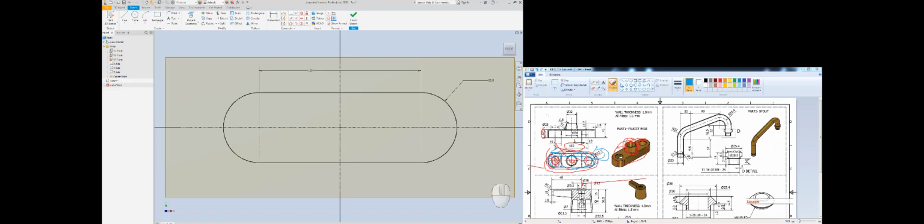We first create the bottom side here. We will just create the base part. I will just finish my sketch and have the extrude and select this face. Here I have the dimension for 25 millimeter in size. I will just erase this dimension and give it 25 millimeters.